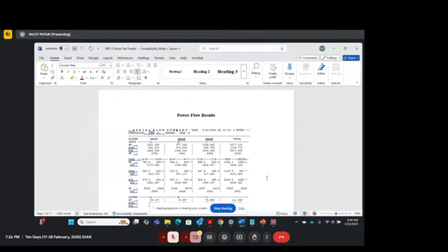So if you have an OpenDSS model of the 13-bus system and you take exactly the line configurations, the same exact connections and everything, R and X values and everything, and at the end of the day, if you can't reproduce the same power flow results as given here, then you cannot validate your model, right? There is some bug or something you're doing wrong.